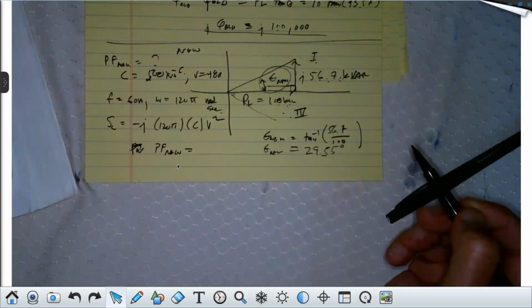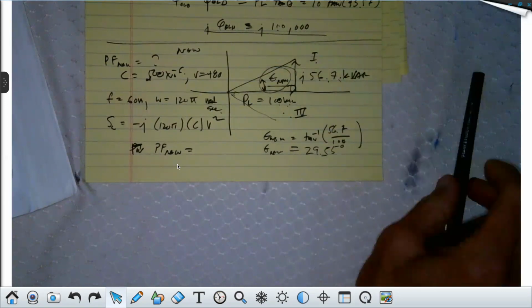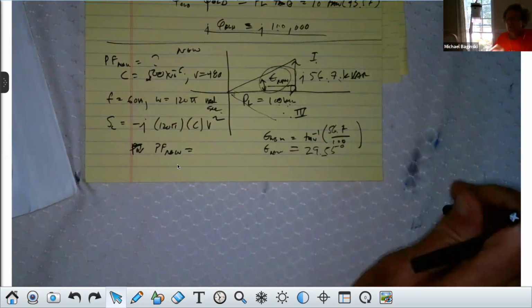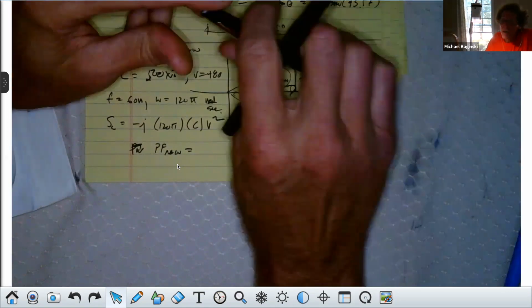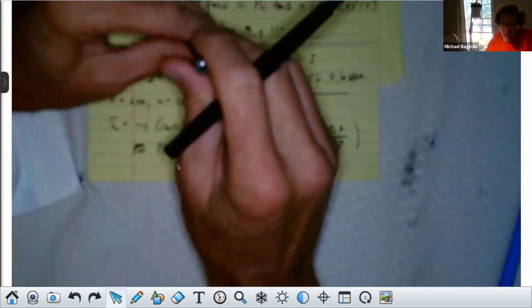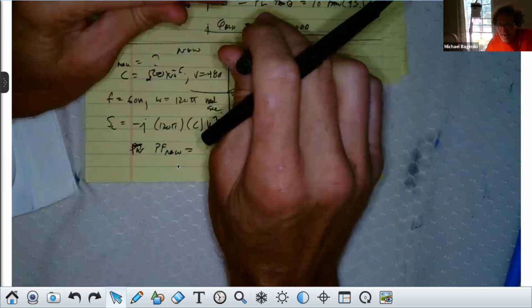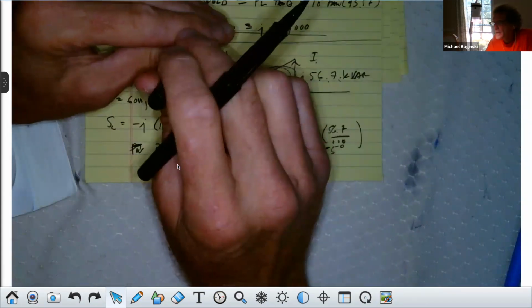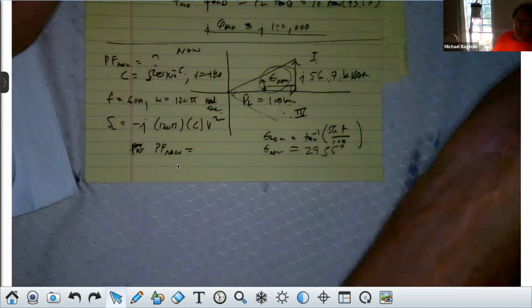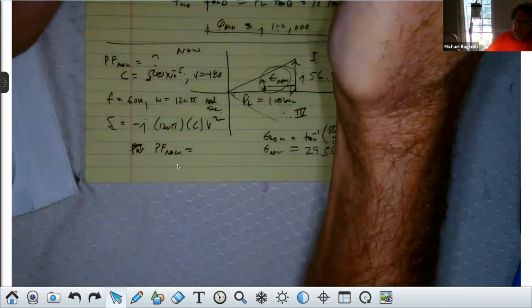I thought you said it was the opposite. Did I just mishear that earlier? No, this is the actual complex power, right? The angle associated with the current, if something's lagging, the current would have a negative angle, right? But when you take V times I conjugate, conjugation turns that negative angle into a positive angle, doesn't it?